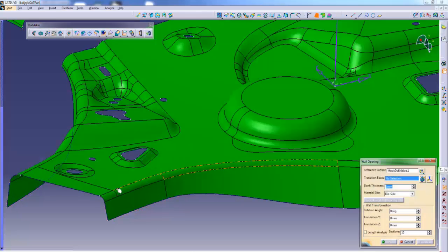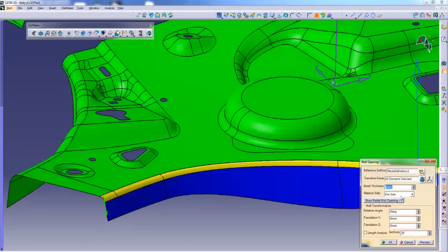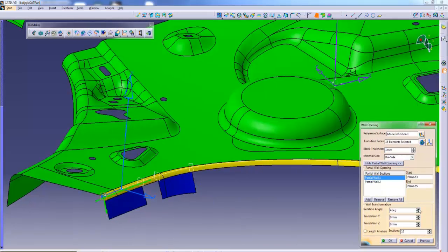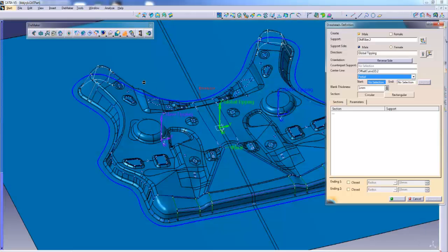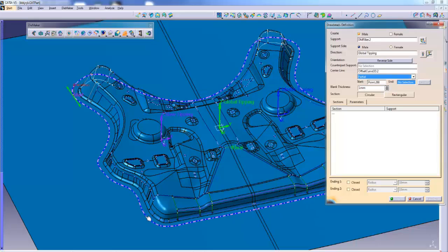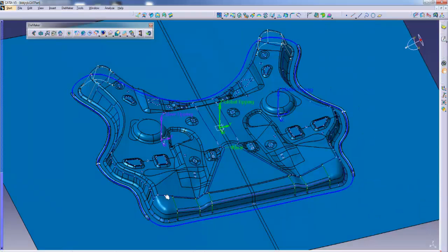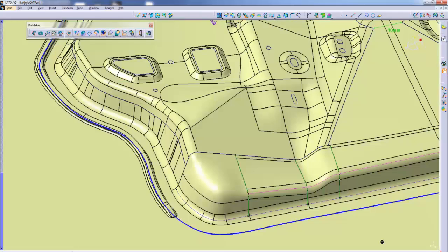Several functionalities are implemented to modify the part geometry itself, if this turns out to be required to improve the formability of the part. Walls can be opened, part radii can be modified, and gainers can be quickly added. Of course, drawbead centerlines are easily created, but also geometrical drawbeads are generated within few clicks. Not only one side of the draw bead can be created, but both male and female side can be considered.